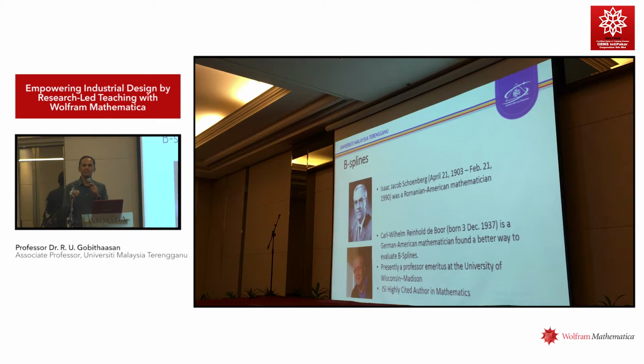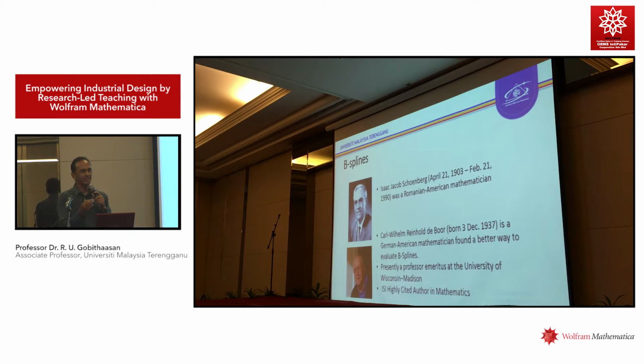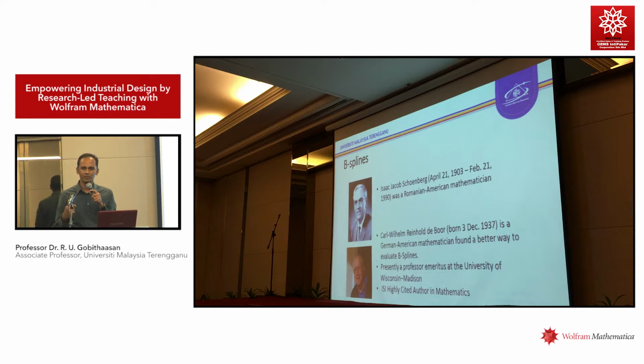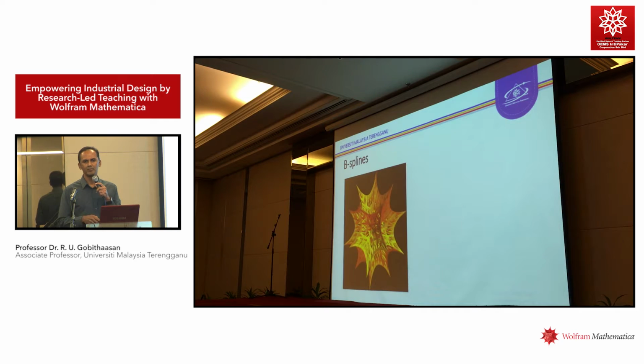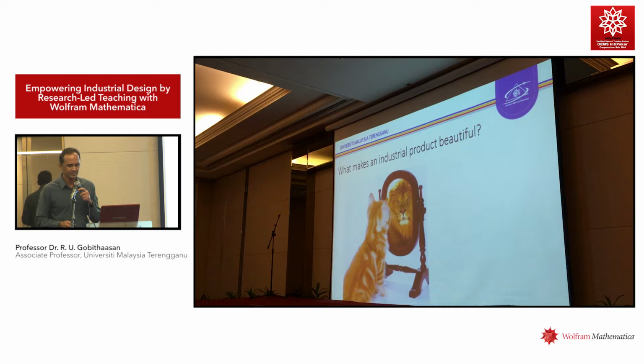At the same time, you can accelerate. Of course, when it comes to CAD systems, you do not use polynomials. You use a shorter way called the de Boor algorithm, by this guy called Carl de Boor, and he's still working at the University of Wisconsin. So you can do things fast with Mathematica. At the same time, you get to understand the behavior of the curve and move forward from there.